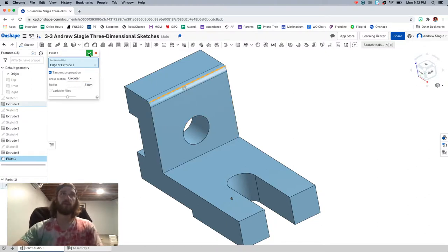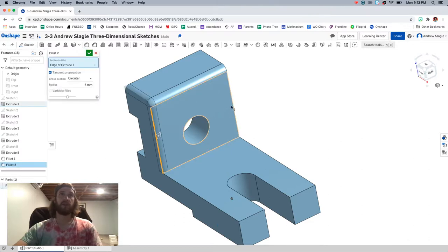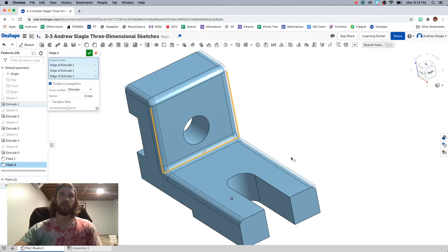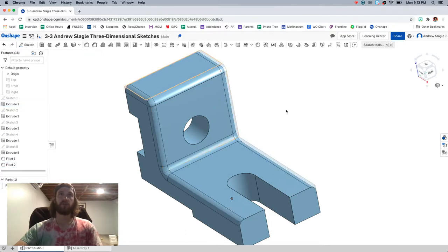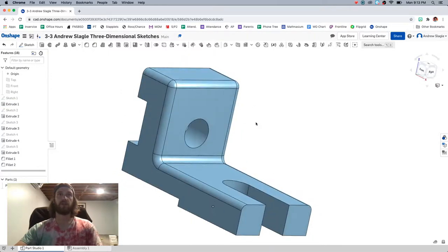So go over there, we can press, hey, I'd like to keep that rounded. Maybe you want to round this too. Let's keep that 5 millimeter rounding going on. And you can even round these interior edges like so, okay? So lots of cool stuff going on. You can make nice rounded edges. The one that's given there, you're rounding these 2 front edges.